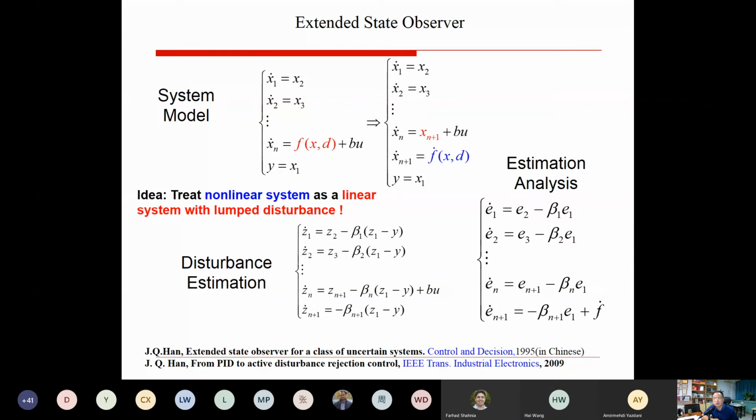You notice that in the Panasonic servo driver I showed, there is also a third term about the friction load torque, the friction compensation. That means in the practical case, even if you use PID, for the low speed working condition, usually we have PID plus friction compensation.